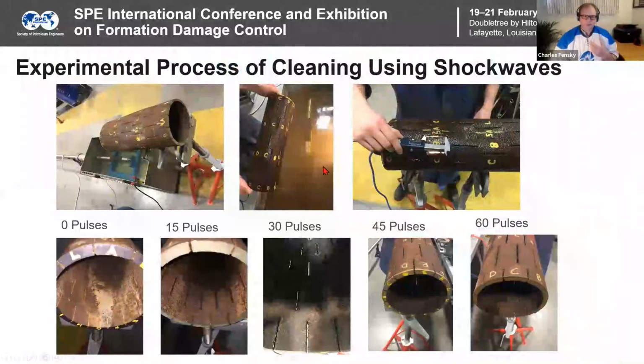In this paper, the key element was we took 4 pieces of downhole completions that were recovered to surface. These 4 pieces had different types of scale that were causing blockages in the flow path. Then we used the downhole tool to apply those high power shock waves to that particular device, and we measured the resulting opening that occurred from the application of those shock waves.